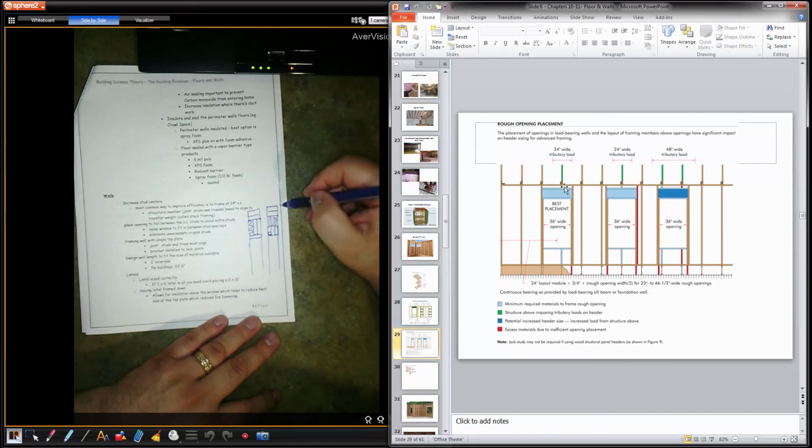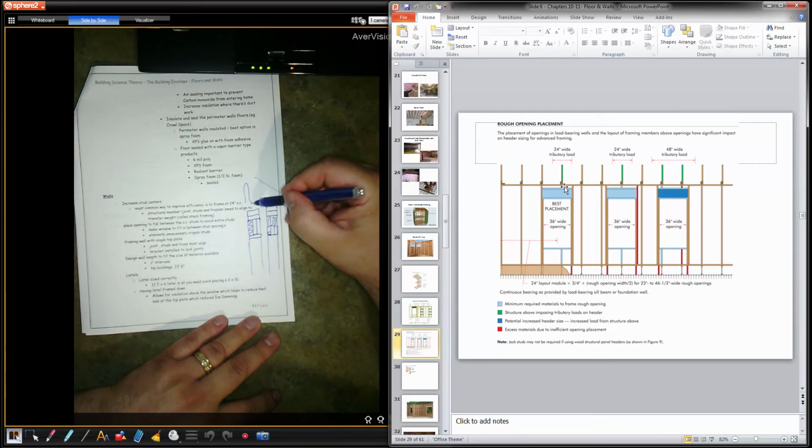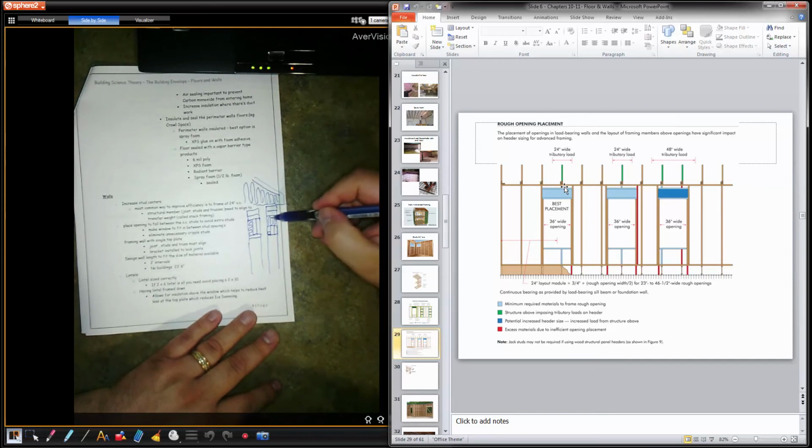So on a house, that's your roof. This is our area where insulation gets compressed, right? We have insulation coming in, and all of a sudden it gets compressed. And we have venting here. So if we have this effect happening, a lot of heat can escape there. We have wood here, wood here, wood here, wood here. Very cold.